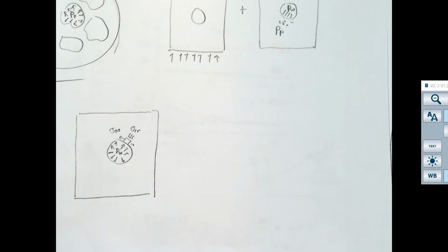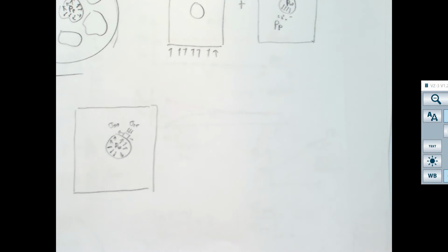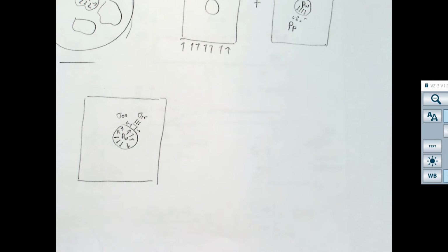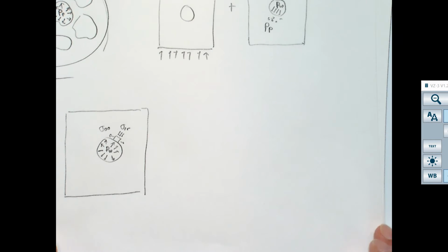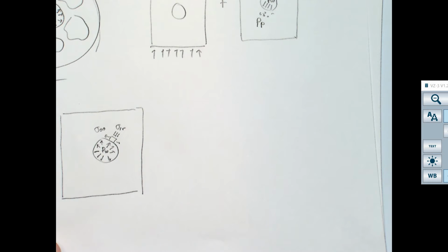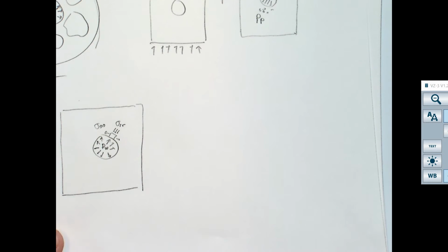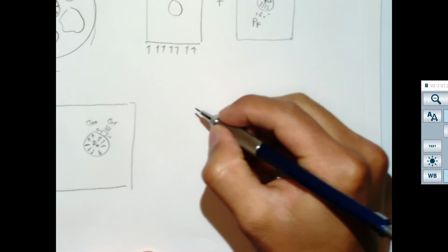Let's go with the easy one. What about radial stress? What is going to be the value of radial stress? PW. Why? Because it's applied radially, and in order to be in equilibrium, you are applying to the rock a pressure, and we're assuming now that there is no porosity, no permeability, no nothing. So if you apply a pressure on it, the radial stress is just going to be PW.